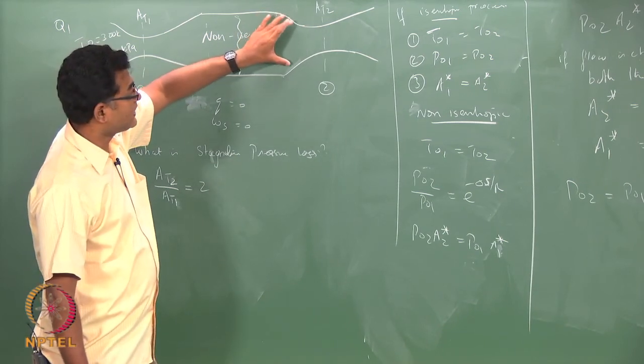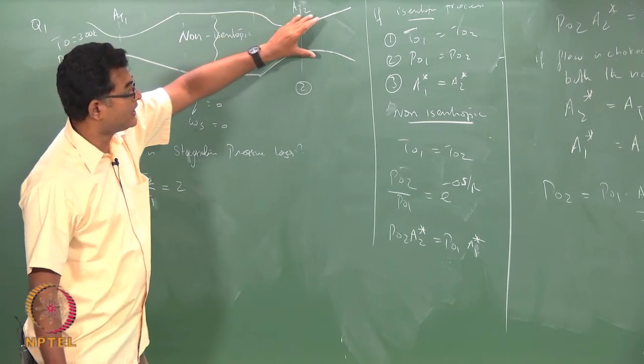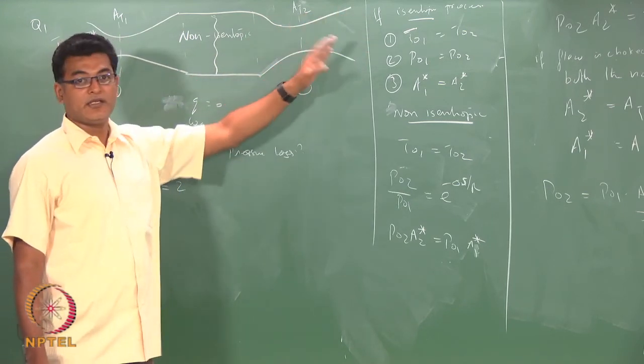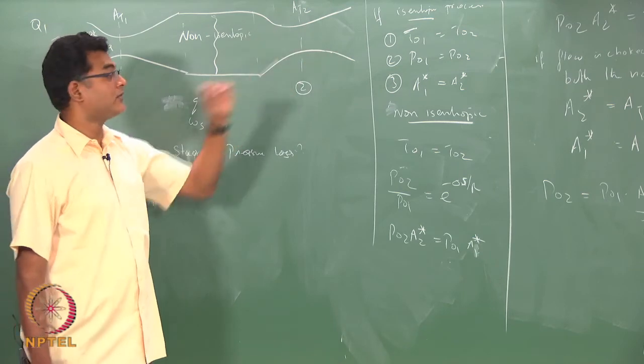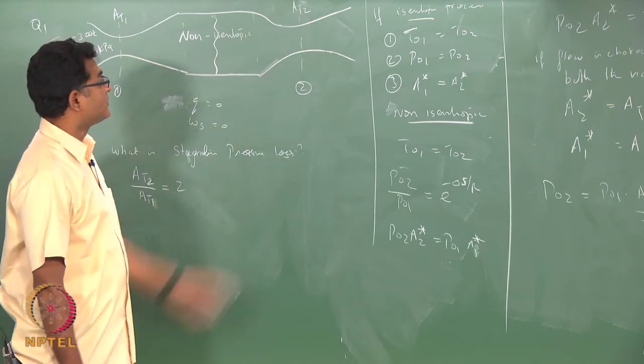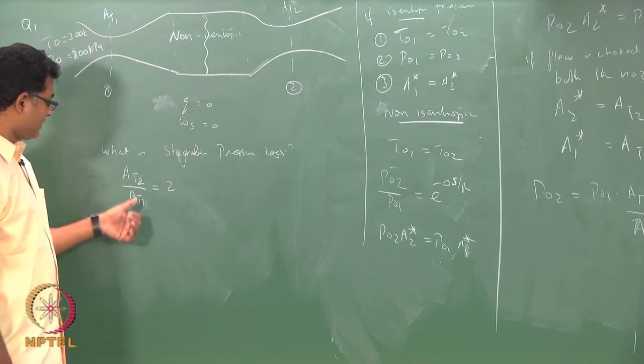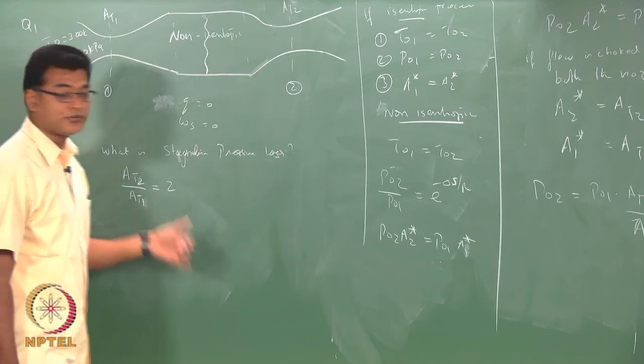So, this would act as a diffuser and it would eject into the atmosphere slowly. So, there are no back pressures from the nozzle. Okay. So, your second throat would be larger. This ratio AT2 by AT1 is 2.